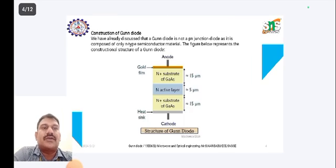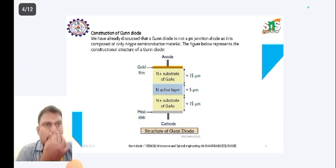Construction of the Gunn diode. See how the Gunn diode is represented here by a diagrammatic, picture representation. Anode and cathode are the top layer and bottom layer. There is a gold thin film in the first layer. Next is the N-type substrate of gallium arsenide, then the active layer, and then another N-type substrate of gallium arsenide, with thicknesses of 15 micrometer, 5 micrometer and 15 micrometer.